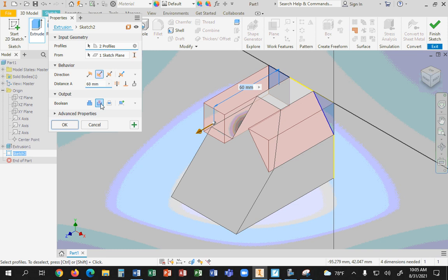In our case, we're going to pick the operation for cutting. Now the question is, how far should we cut? I'm lazy. If I change the shape of this object, I don't want my cut limited to 60 millimeters because my object might get much bigger later, yes? So there are two ways. One is through all. I find through all to be slightly annoying, especially when I start adding geometry later on to this thing.